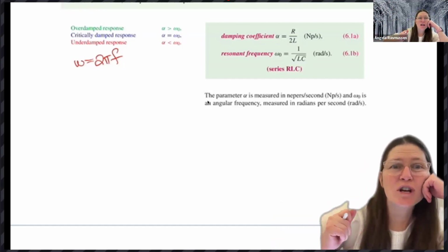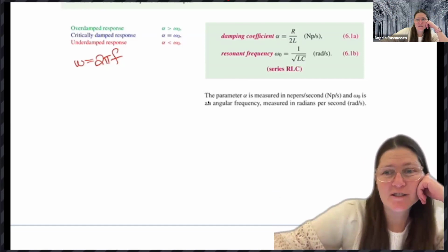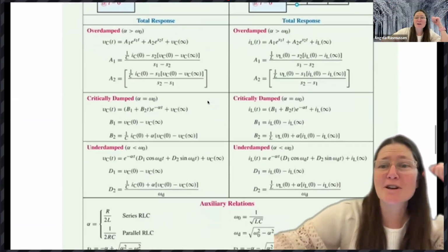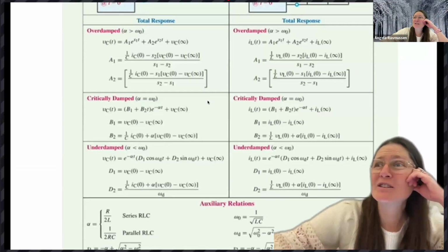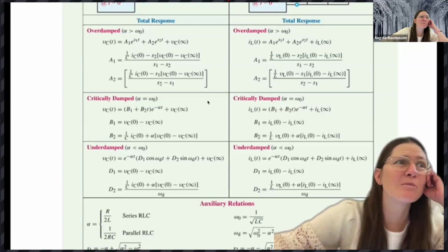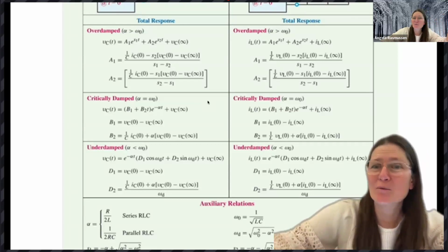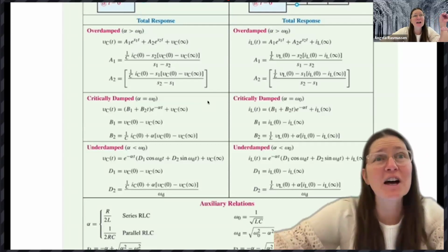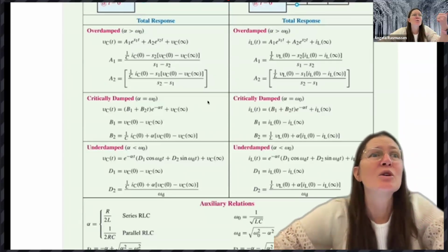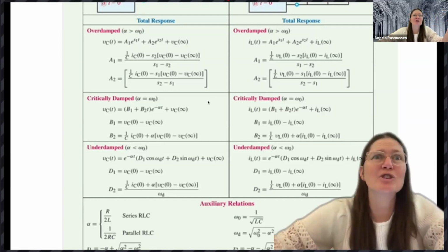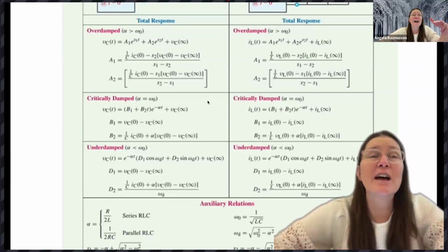All right, so now when we're solving these kinds of circuits, we know that we have some general forms. I'm not going to go through all the derivation because we don't need to. We already know where it comes from. If it's of this form, then we're just going to use these equations. We will need to find every value within there with those 3 redrawn circuits: an initial circuit, a final circuit, and then we use final values.